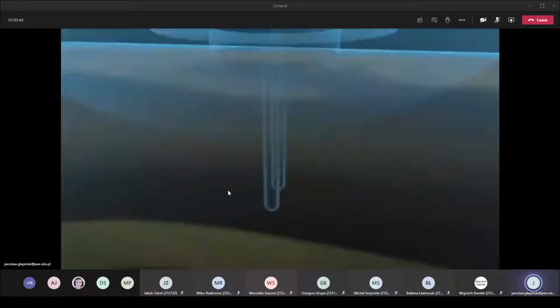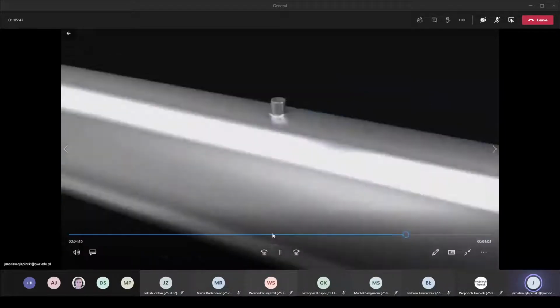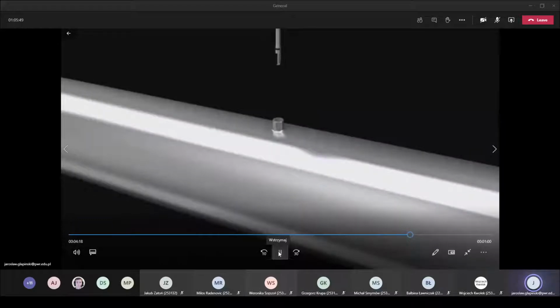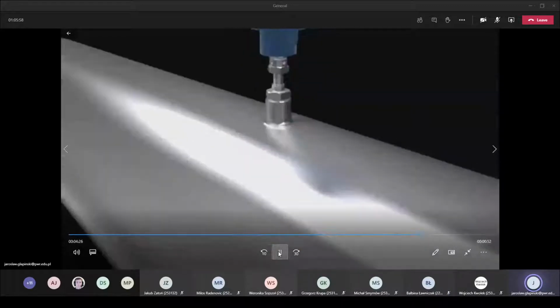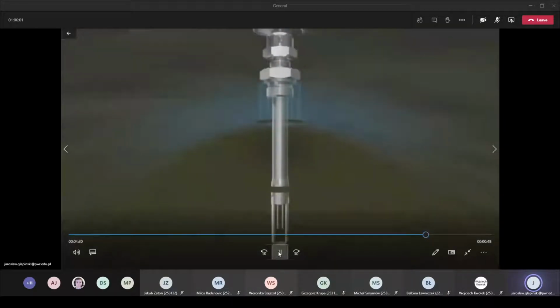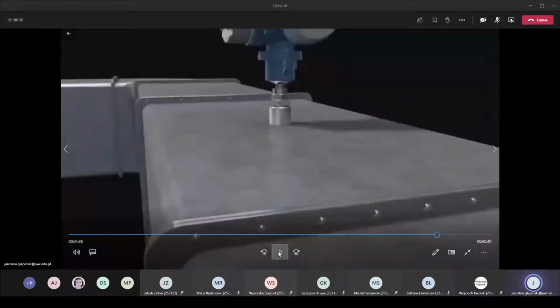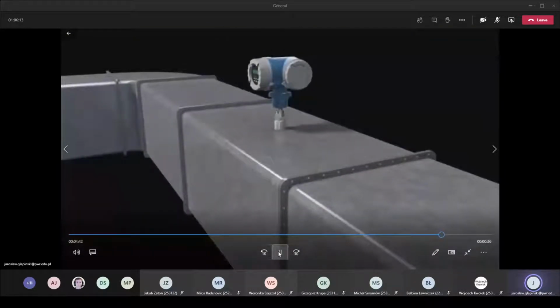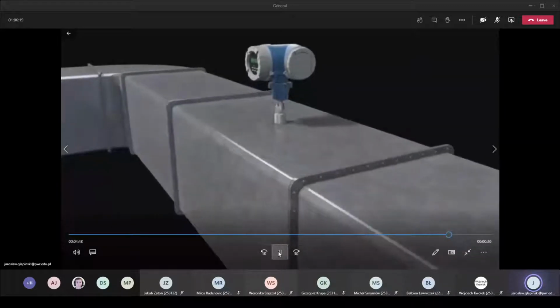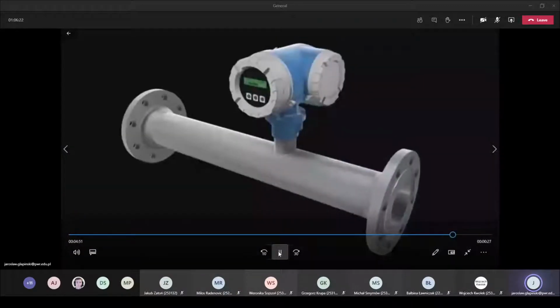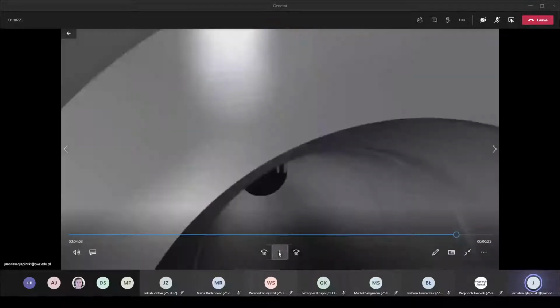Flow measurement using the thermal principle is also possible in large pipes and ducts. There are meter types designed specially for this application. They can be inserted directly into the pipe via a standard process connection. It is important that the required insertion depth be respected so that the measurement is carried out at the correct point. For that reason, it's essential to program the actual internal pipe diameter for all insertion meters. Correct insertion also applies for rectangular and square ducting, often found in factory or building air circulation systems. With thermal mass flow meters from Endress.